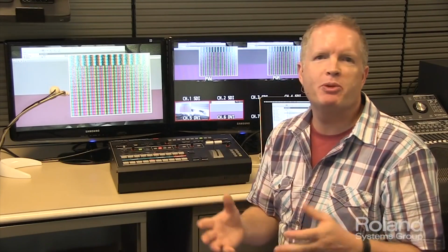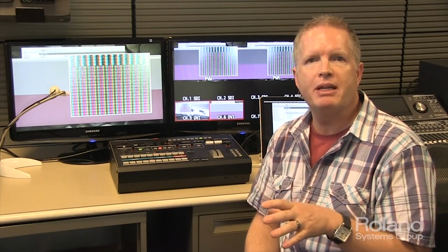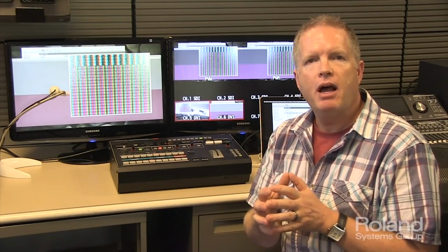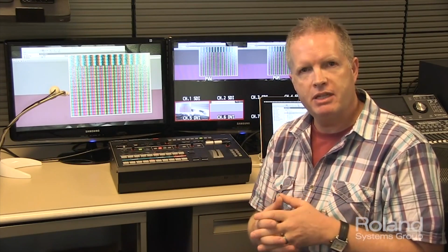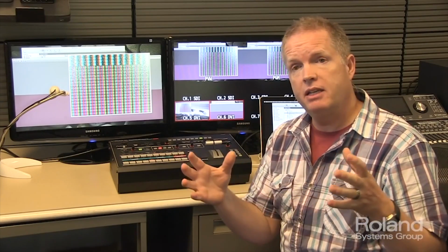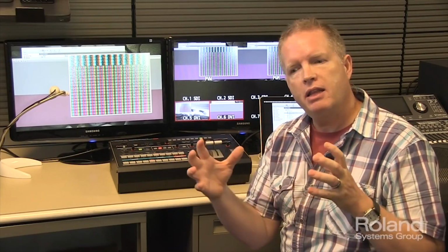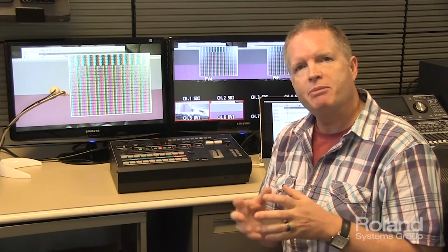Today I wanted to show you a real practical difference between 444 video processing and 422. Now what do those numbers really mean? Well, it really refers to color or chroma sampling, how color is sampled within a particular video signal. And the reason why compression even exists is to make the data stream required a little more compact, a little less bulky.